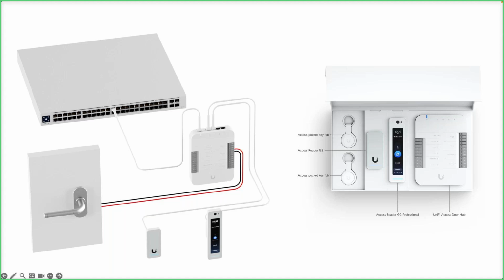And then from there, you can take that PoE power and pass it through to the readers as well. So those two readers that are connecting downstream from this are just getting powered via PoE. And the reader itself even has a 12-volt relay, so a 12-volt 1-amp relay. So if you want to do basic mag and strike locks, it's a perfect solution for that. It can even power those things as well.